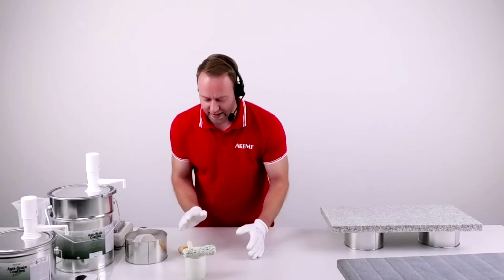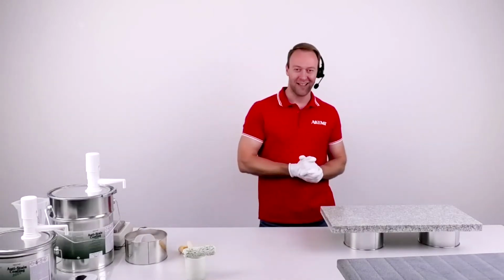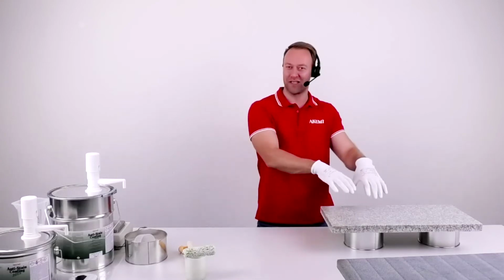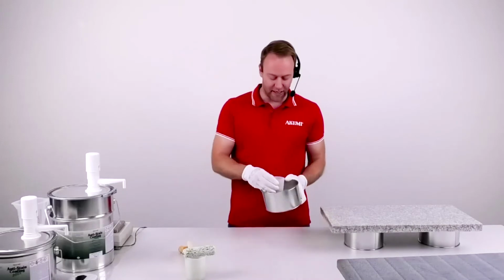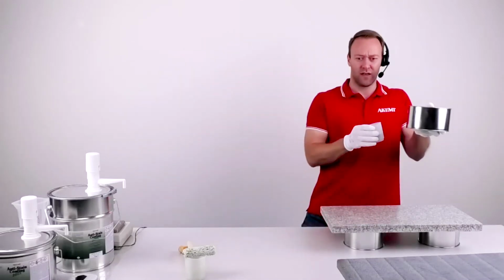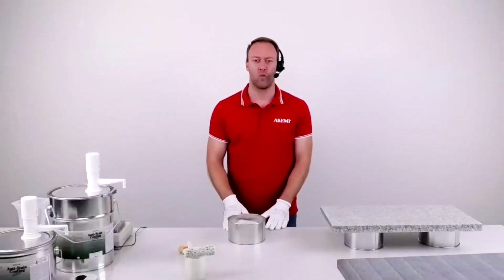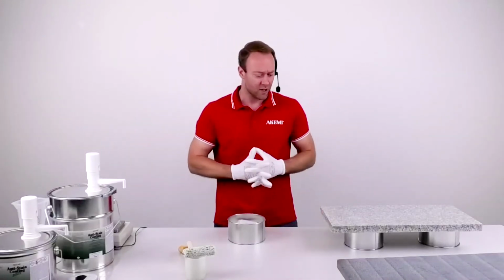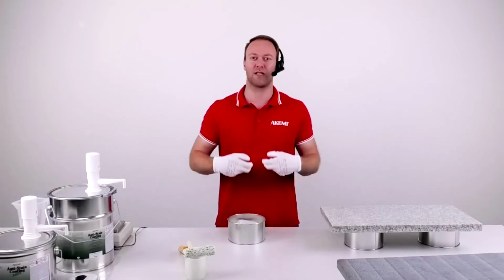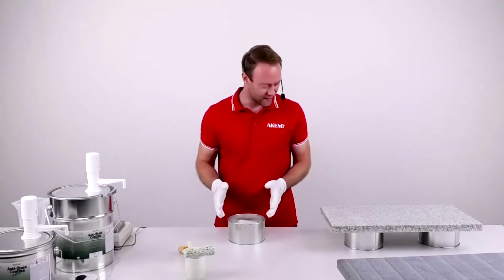Of course, now I could install it. If I install it like that, it's perfect protection, but tile adhesive will not stick there. For that, I need some washed quartz sand. I can show it to you here. The size doesn't matter actually. It's about 0.5 to 1.5 millimeter, plus minus, so that's not so important. Important is that it must be washed. No dust should be there, only pure quartz sand.